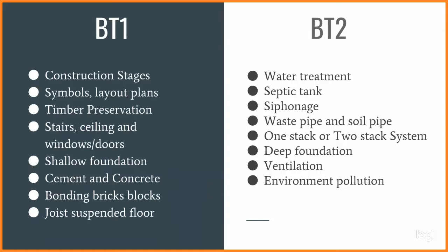Septic tank, siphonage. Let's say you have a certain overflow of your septic tank. Then this septic tank during heavy monsoon downpour will be flooded. So the waste inside, the human waste inside, would actually float out. If it floats out, goes to the drain, and then goes into the same water system, it's going to pollute drinking water. So all these are issues about back siphonage and treatment of water.